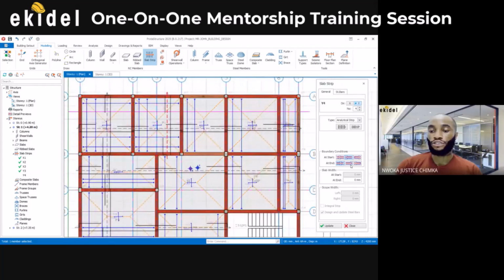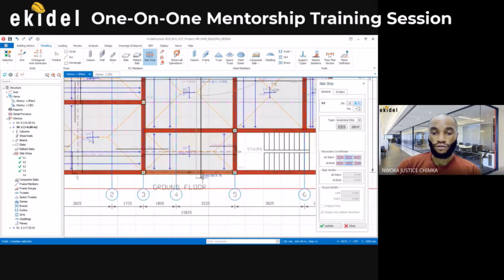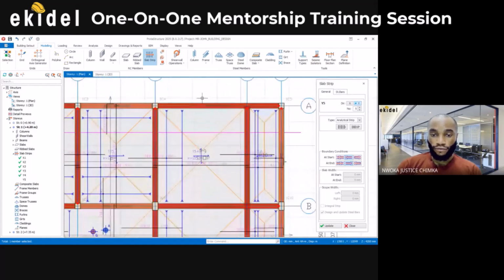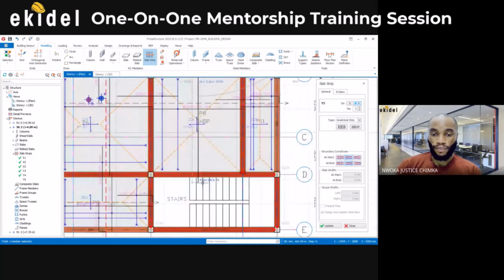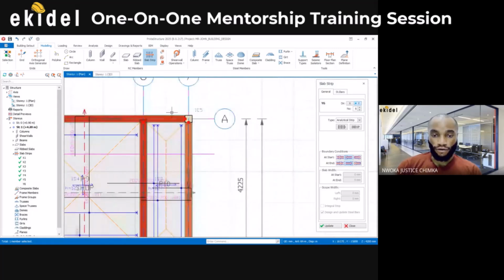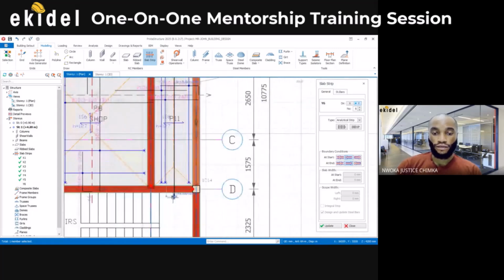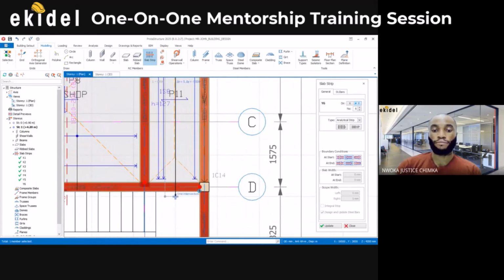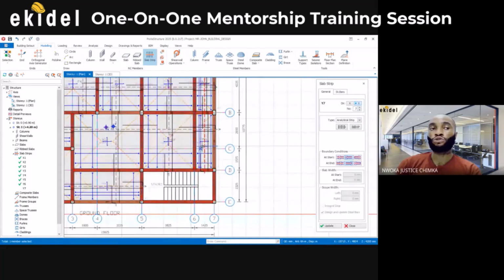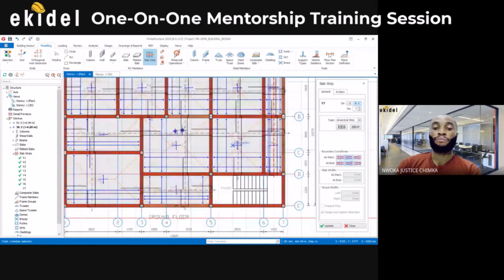Okay. I'll now change to beam to beam, and I'll cut from here all the way down here. Okay, and again, from here all the way down here. And again, the last one now, from here all the way down here. Correct. So right now, had it been the depth is not sufficient, while you're cutting, it will show you a warning that the depth of the slab of that panel you're cutting through is not sufficient.